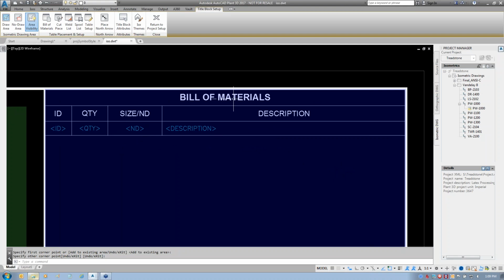It's got my bolder, larger text for the title, using Arial there for my headers. And those were just textstyles, AutoCAD textstyles. And then it's using the 1/16 inch high text there. So it adjusted those heights and things based on the textstyles I set up there in the ISO theme.